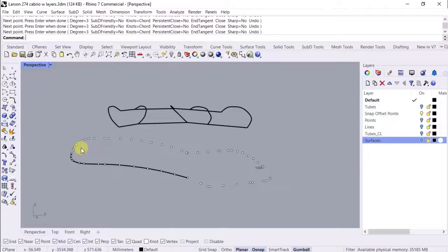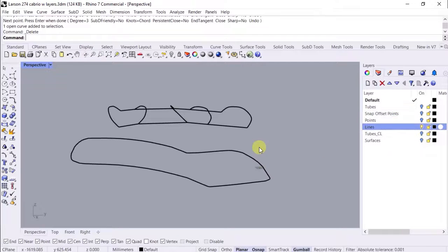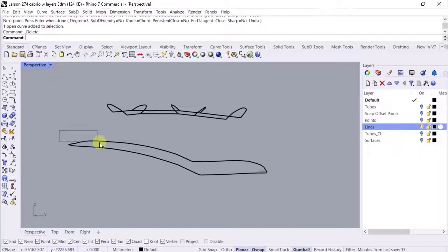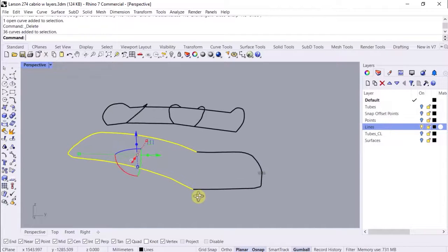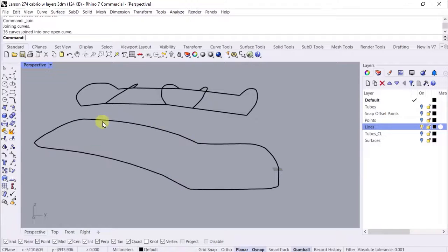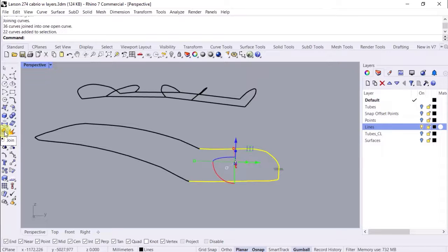Alternately, a faster method uses the line generated by PhotoModeler. Turn on the PhotoModeler Lines layer. We join the front half by selecting just those lines, as we want to keep a sharp transition front to back. Pick the Join command to make one polyline. We repeat that for the back snap line.